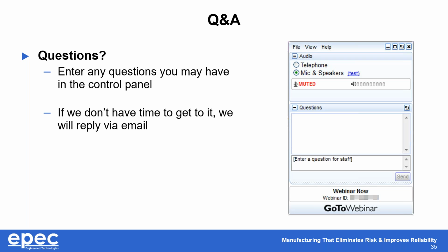Next question is, what's the best D-sub equivalent connector that's low cost but suitable for a high reliability application? So the best way to respond to this is just agreeing that the assembly type off-the-shelf D-sub connectors, if you've built your own D-sub cable, you're familiar with what I'm talking about. It's basically a hood assembly with some connectors and thumb screws. You put it together with a cable, kind of like a clamshell design. Those can be $5, $10, even $50 if there's something fancy about it. But we discourage using those in our high volume setting because it's expensive.